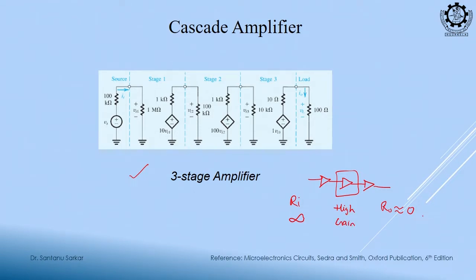Okay. So, this amplifier should be selected so that this one gives high input impedance, this one gives low output impedance, and in between we have high gain, A1 into A2 into A3, which should be our total overall gain, right. If you see how the amplifiers are connected, the first one has an input impedance of 1 meg, which satisfies our first criterion.